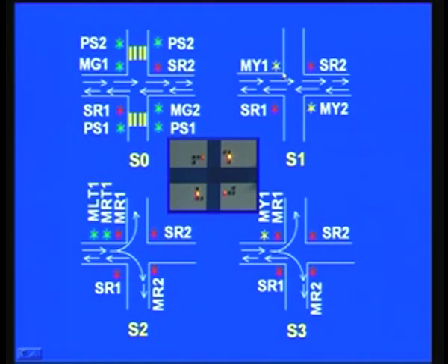When that happens, we have removed the pedestrian crossing because it is much safer before the oncoming traffic in S2 here, which happens to be the left turn as well as the right turn, and corresponding signals are all lit here, and we have now the left turn. This is an extra addition here, and this was already there. Next, once again it will go through the yellow as far as main traffic is concerned, and that is the S3 sequence.